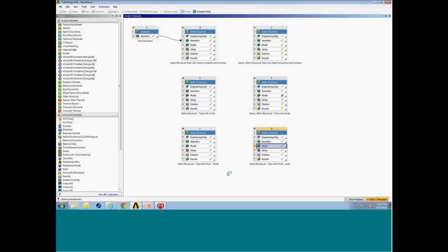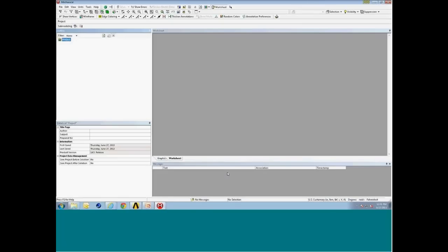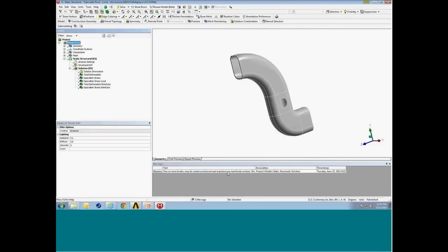While that's coming up, submodeling is a useful tool many folks employ to determine detailed stresses in parts. Quite often, a larger model may be too coarse. It's important to get load transfer, but too coarse to produce satisfactory results in a specific region, such as a stress concentration factor. So many times you want to build a detailed, solid model of a localized region to get the detailed stresses you need. So in this example, we have a shell to solid submodel.